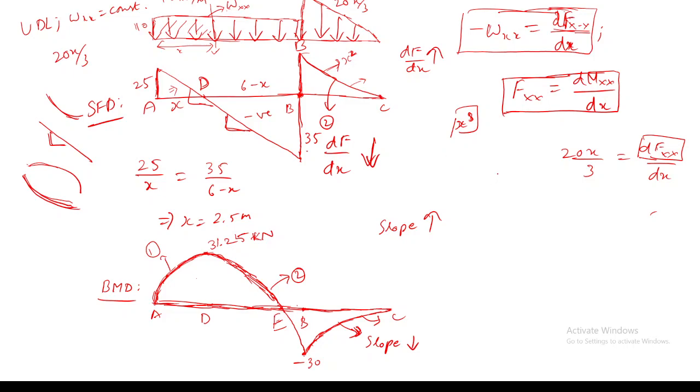So in our diagram, at point E on the SFD, if we try to plot, then it is not corresponding to maximum shear force because there is a mixture of loadings. They are having concentrated shear force loadings. So it won't coincide with when shear force is maximum, like bending moment is 0. That won't occur.